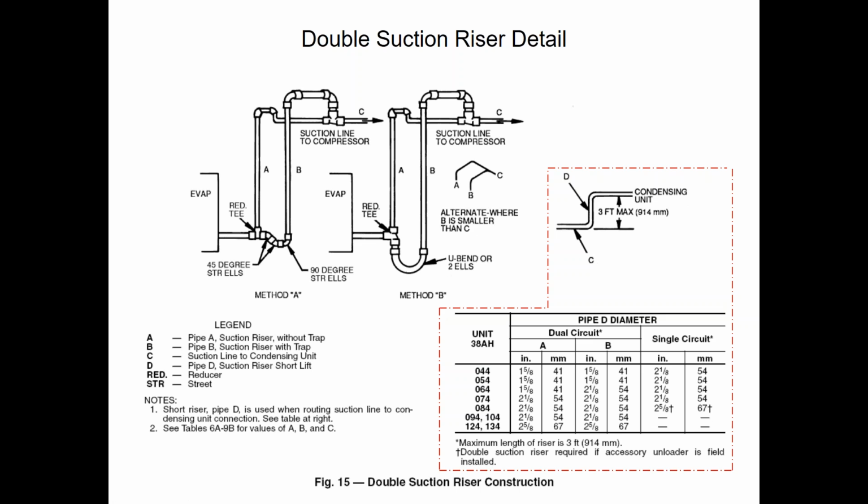Lance asked, when you refer to oil, are you referring to the liquid refrigerant? No, when I'm referring to oil, I'm referring to the compressor oil, like POE with 410 or mineral with R22. I'm talking literally the compressor oil.